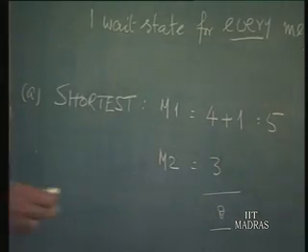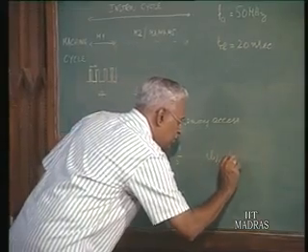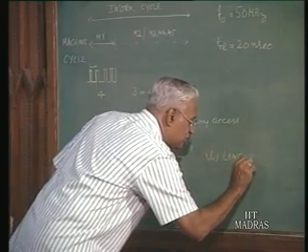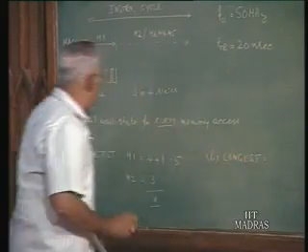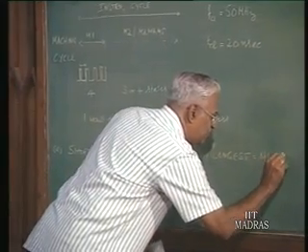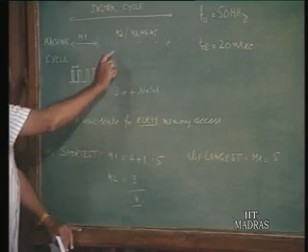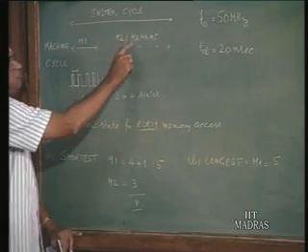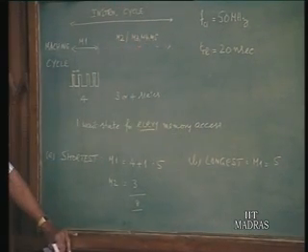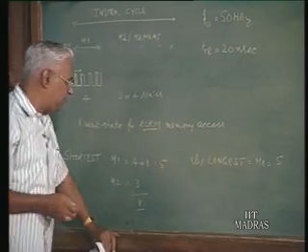Then the longest instruction execution will have M1 as before, no change, 5 states. Then we have M2 to M5, that is 4 machine cycles, because for the longest we have to include all of them.